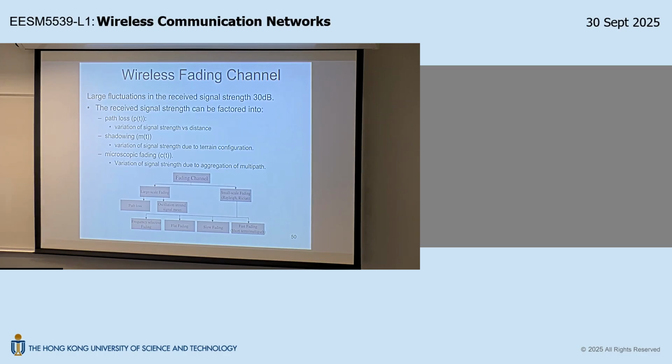So is the coaxial cable time invariant? Yeah, of course, you will guess it must be time invariant. But why? How do you know? Again, you look at this circuit model. All these L and C are basically time invariant elements. The capacitance and inductance are not changing with time. So therefore, the circuit behavior would be time invariant. That's one way to look at that.